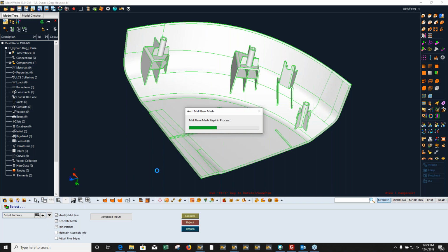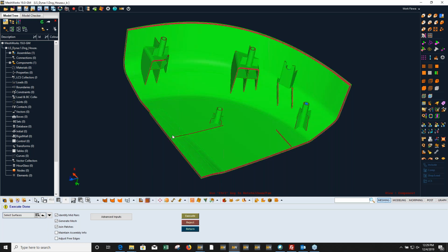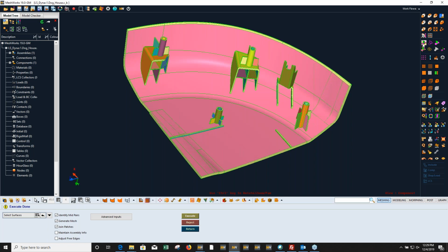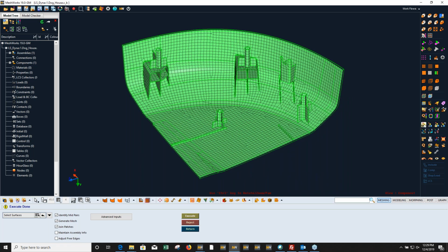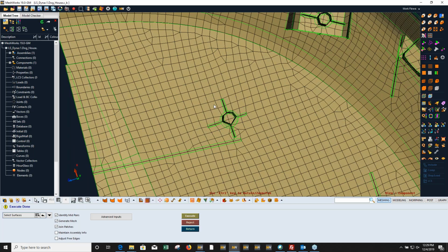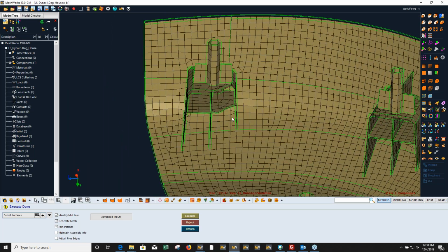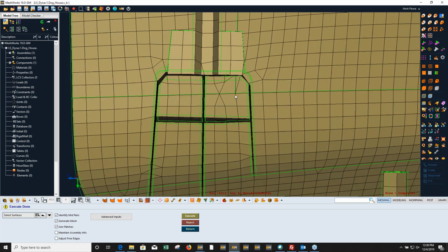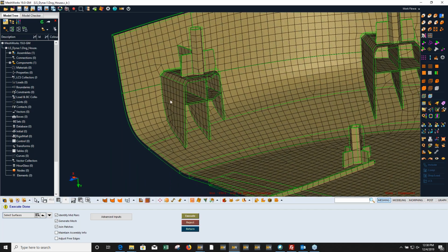So the entire process of the meshing and then the subsequent thickness assignment based on the draft angle, that is also a fast, easy process within Meshworks. So components big and small, which are heavily ribbed, thin-walled components like plastic parts or thin-walled castings, etc., can have a great advantage with respect to this modeling. So it's already done. So now we will show you the results. All right. So you can see with no intervention from the user, it nicely connects, extracts, stitches, and connects the entire model together.